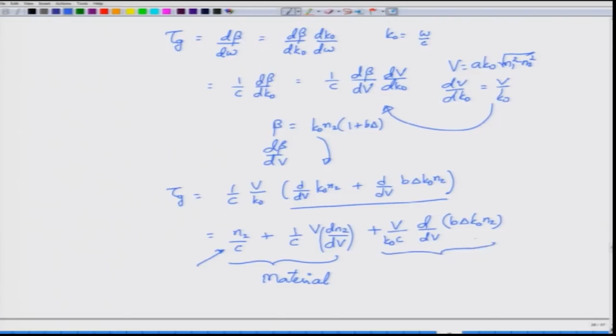But the term that is there on this right hand side is what is called as the modal dispersion. Okay. Modal dispersion in turn can be broken up into inter and intra, which means that if I am going to consider only a single mode fiber, the propagation constant B will be different and it will be nonlinearly related, but it will still be with the same single mode, right. So, this is called as intramodal dispersion.